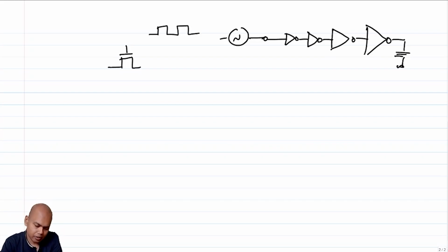So we understand the fact that the power consumption, if I have a capacitor C and I have to switch it, the power consumption associated with the capacitance is C VDD squared F, right? Where F is the switching frequency.